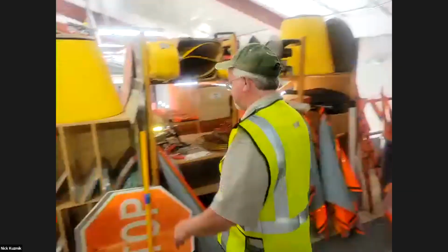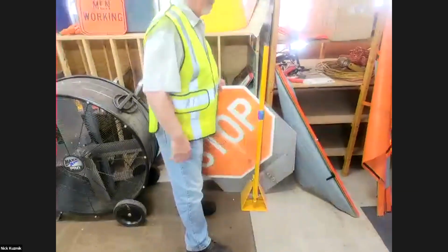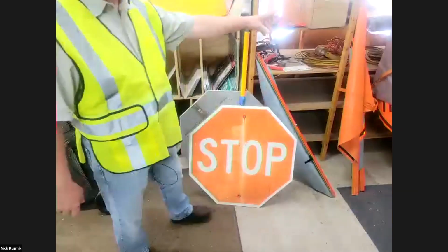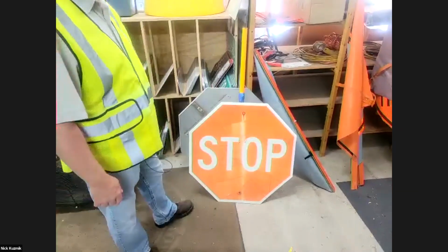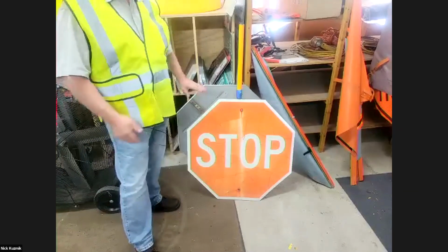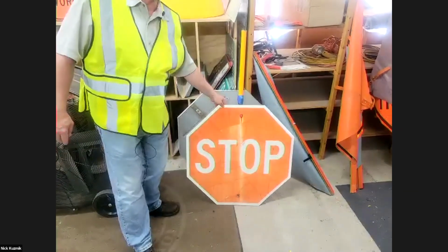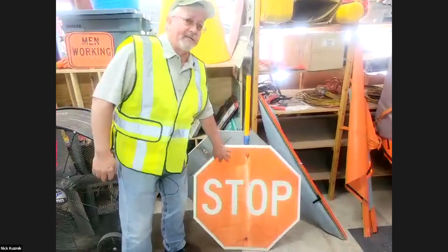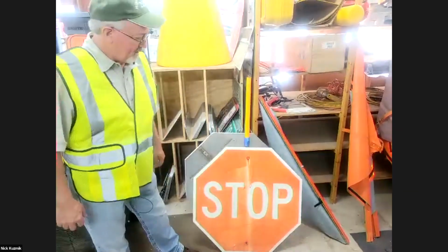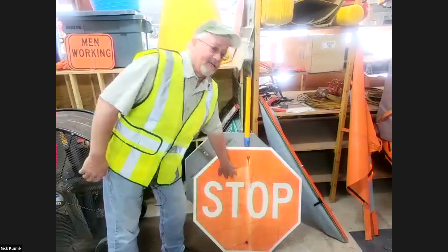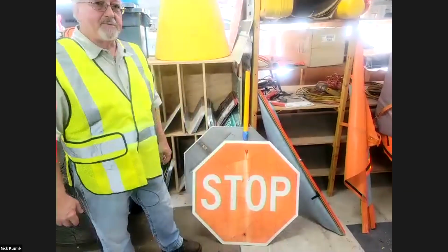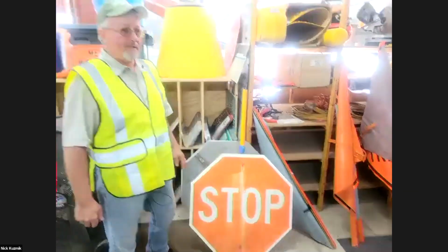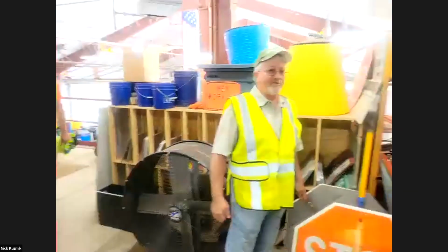As far as signs too, if you're using signs that you have there, if they're faded, if they're worn out, you don't want to use them. And again, these need to command attention. You need people to be able to see them. Obviously, this is a stop sign that has outlived its day. You probably can't see this at night. Again, the contrast between the red and the white is probably kind of blurred out and it'd be difficult to see, but the same goes for work zone signs. You definitely want them to be clean, want them to be visible.